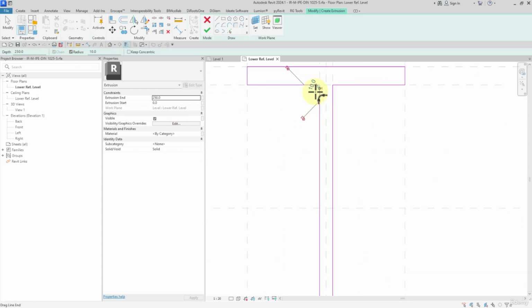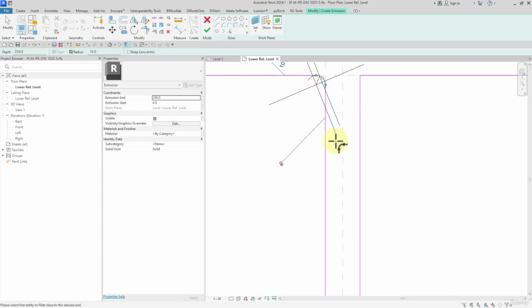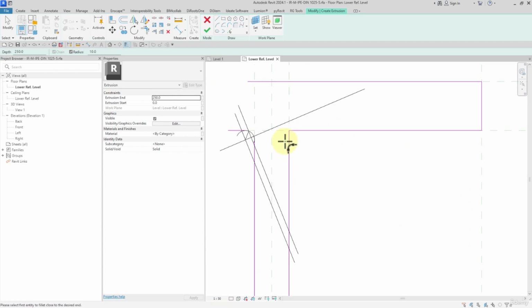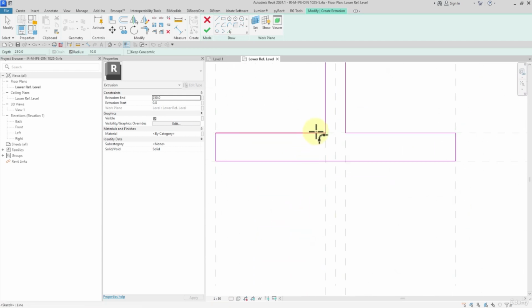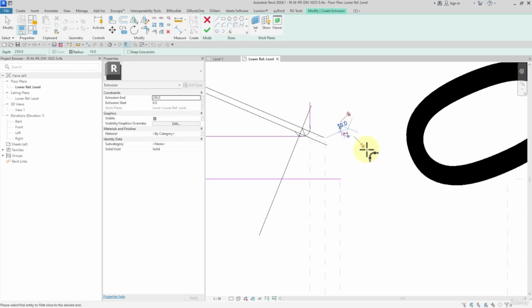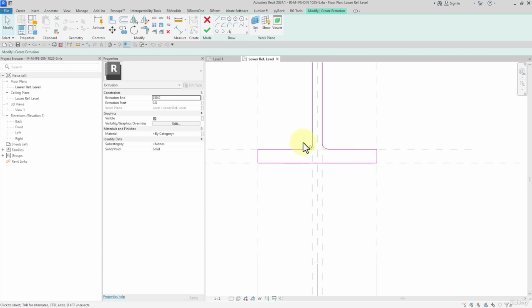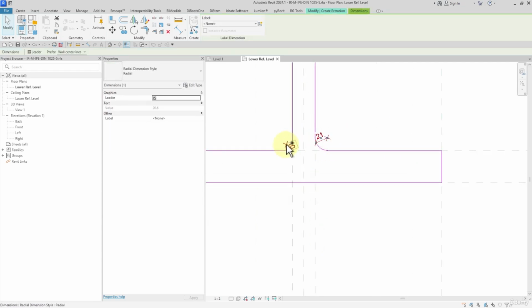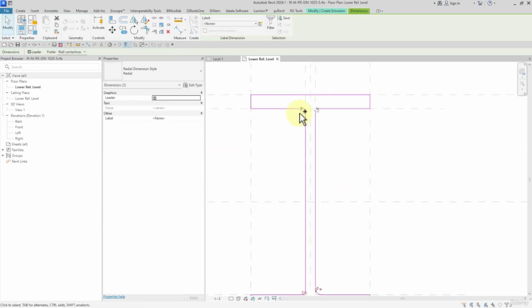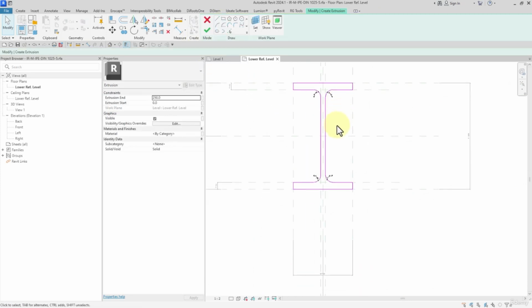radius, and then I specify 10 degrees. And then I choose to show the dimension with 1 to 50 scale. Then for the bottom part, like this way. Well done. Great. And then 1, 2, 2. Then I select them again. I select the fillets and then I associate them to F. Well done. By this way.